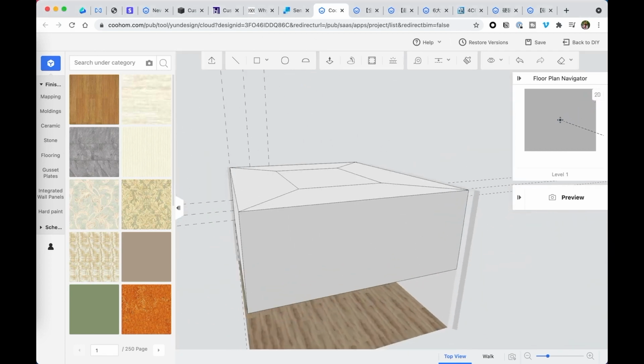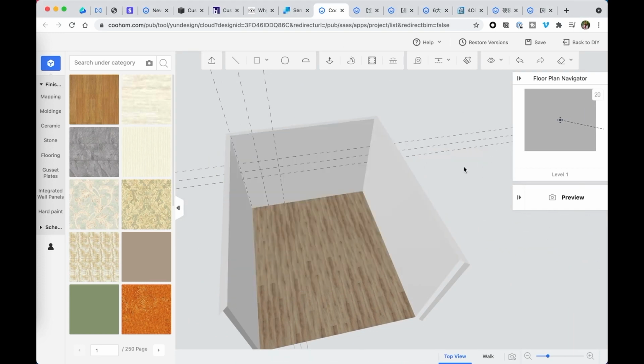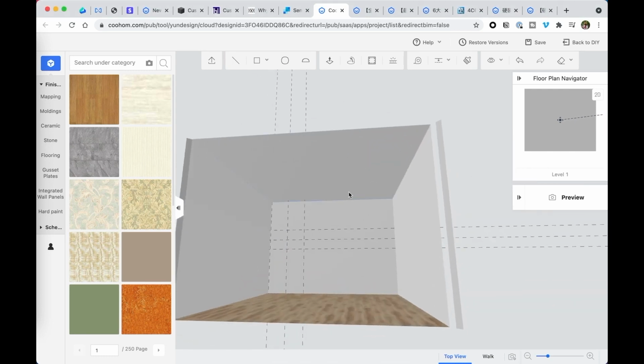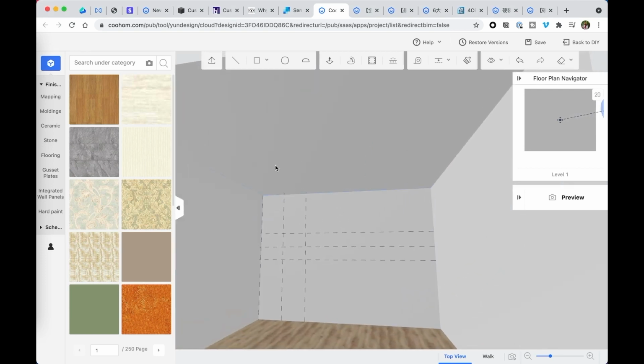Go back to it, delete all the ceilings, delete the surface. Okay, let's delete all that. In this case, we'll do something, a combination of the push and pull and also the grouping tools. So first, we just need to draw the taper ceiling here, like how we did it here.